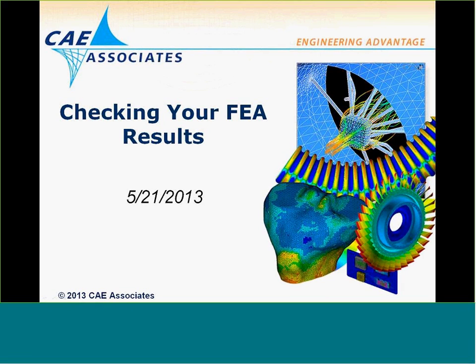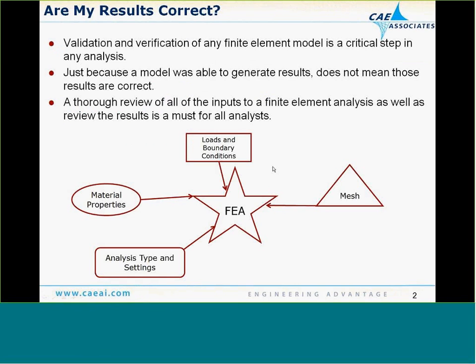We're here talking about checking your FEA results. And obviously, any validation and verification of any finite element analysis is an extremely important step. Just because you were able to get a solution of your model doesn't mean that it's correct. A thorough review of all the results and all the inputs into a finite element analysis is a must for any analyst doing finite element analysis.